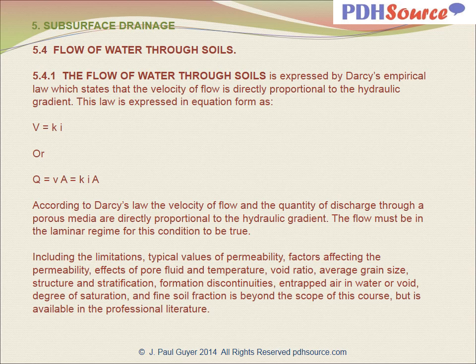According to Darcy's law, the velocity of flow and the quantity of discharge through a porous media are directly proportional to the hydraulic gradient. The flow must be in the laminar region for this condition to be true.